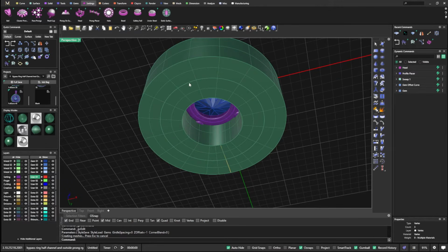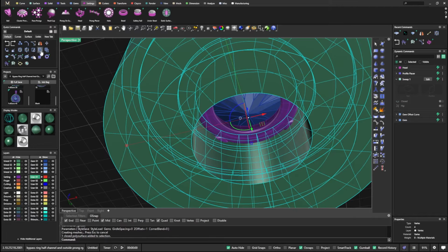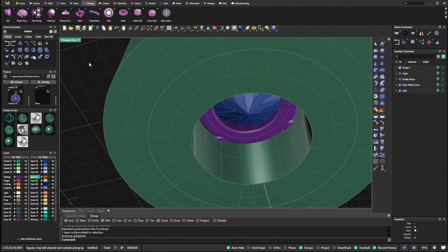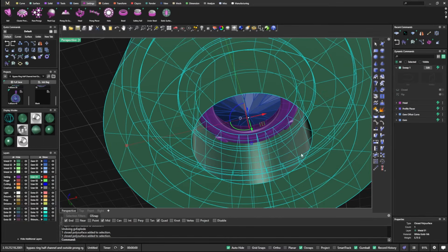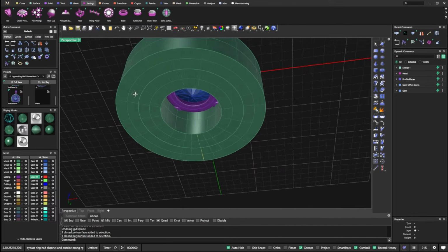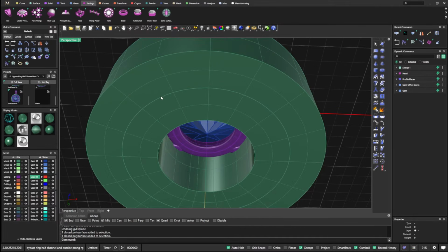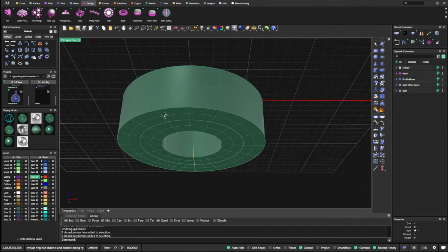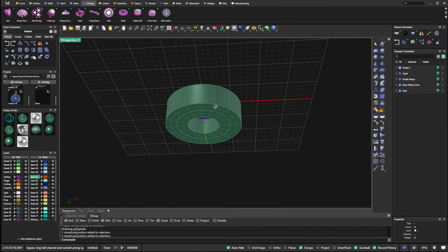And we have a knot right here, it looks like. So if I take this and I explode it, how do I know it's a knot? Because see that real thick line versus these other lines? That's giving me a knot. So I'm going to back out of that, make sure they're all joined together. Yeah, so we got a closed polysurface. You need to recognize where your knots are at, and this next step will tell you kind of why you need to recognize it.